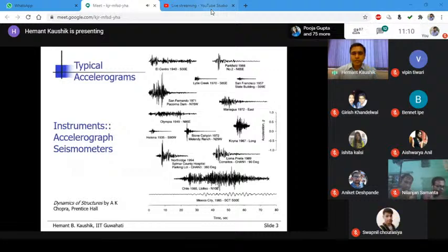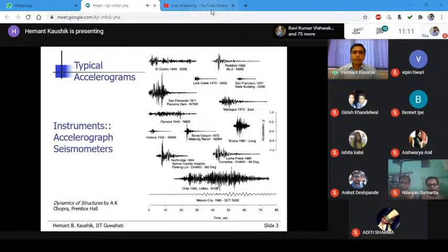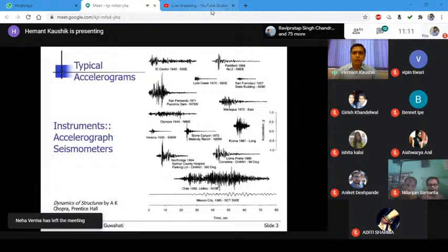The acceleration records are unique for every earthquake. They are the signatures of that particular earthquake. We cannot have exactly the same kind of record for two different earthquakes. It's not possible because of many issues. Primarily the ground is different, the frequencies of the waves are different, the type and the energy that these waves carry is different. The type of instrument, the foundation of that instrument, whether it is located on rock or what type of soil, how deep the rock is, so many factors are there. Therefore each recording is actually a signature, right?